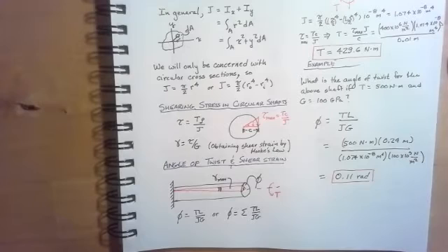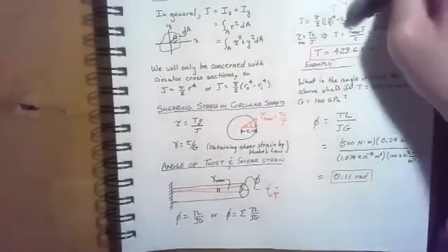And we could have similarly stepped shafts that are subjected to multiple torques. And we could break up a shaft segment by segment and find the total angle of twist as the summation of TL over JG. Now you might notice that this looks very similar to delta equals PL over AE. So yes, in fact, this is analogous to what we've done before with axially loaded shafts, and all of the same types of problems, the indeterminate problems, could also be solved using methods of superposition. However, we're not going to do that in this course.